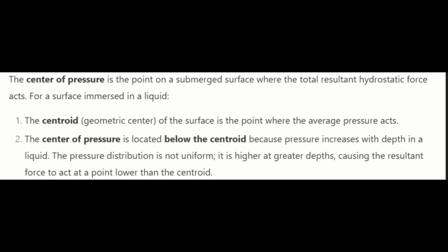Okay, the geometric center, because the pressure increases with depth in a liquid, right? By that formula rho g h, it is directly proportional to that distance. The pressure distribution is not uniform. It is higher at greater depth, causing the resultant force to act at a point lower than the centroid. So any body immersed or submerged in a liquid, its center of pressure will always be below the centroid.